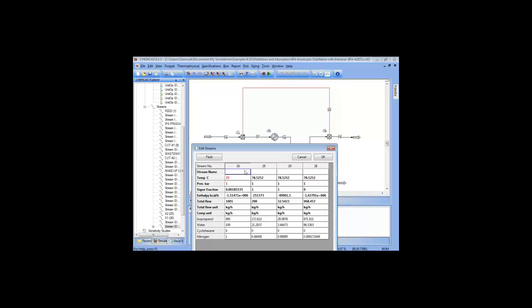At the inlet, and I'll label these streams so they're easier, at the inlet we have 1 kilogram per hour entering. At the vapor outlet, we have almost 1 kilogram per hour leaving. At the liquid outlet, we have a very small amount of nitrogen leaving. The nitrogen in the vapor and the liquid outlet, just from a quick glance, I don't think this adds to 1 kilogram per hour. Looking at the recycle, we've built up, we have 6 kilograms per hour in the recycle. But what I'm really concerned about is, just eyeball glance at the outlets, that doesn't add to 1.